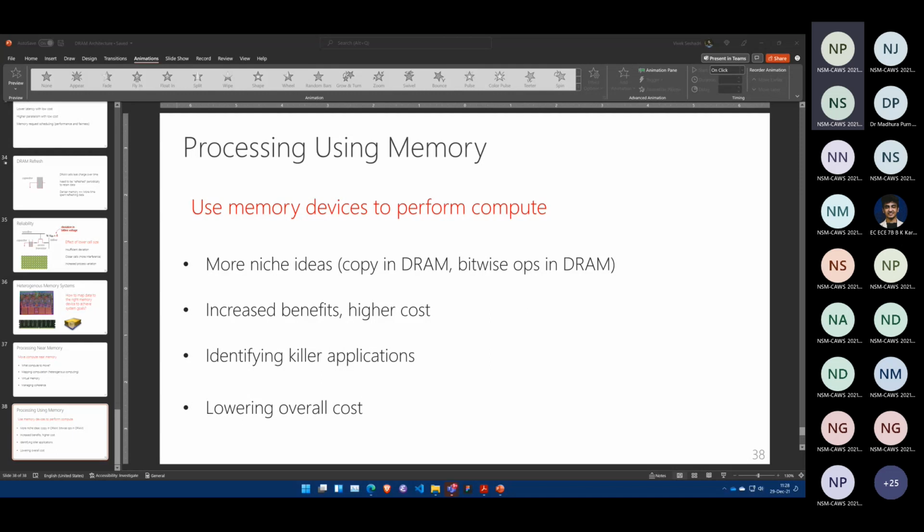It's not a big enough problem for them yet to worry about this, right? So any solution that you come up with should stay within a single layer. Can DRAM manufacturers do something within their layer to reduce the refresh time? Can the memory controller do something within its layer? I think those are the type of questions that people are asking today, or those are the practical approaches that will work today. But there is research in understanding which data is actually used, and then trying to refresh only that data.